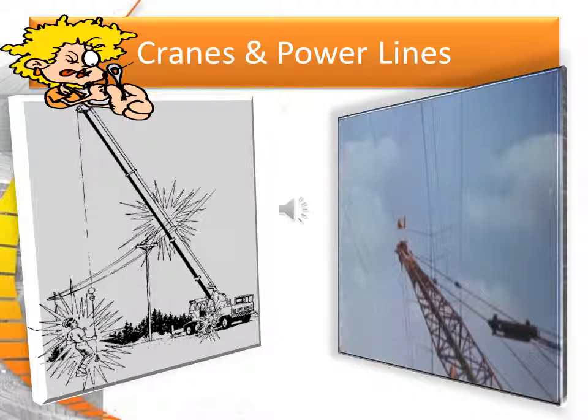Here we can see a depiction of cranes and power lines. Remember that the higher the voltage of a power line, the greater the distance the crane must maintain.